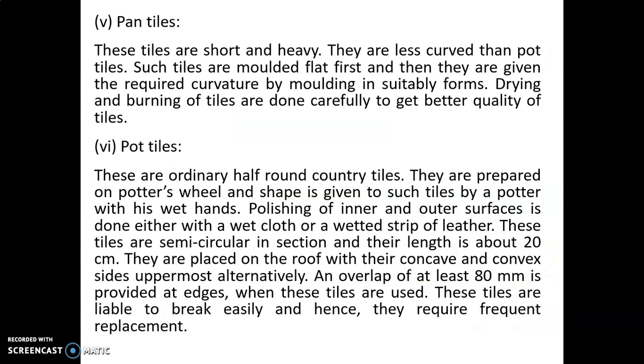These tiles are short and heavy. They are less curved than pot tiles. Such tiles are molded flat first and then they are given a required curvature by molding in suitable forms. Drying and burning of tiles are done carefully to get better quality of tiles.